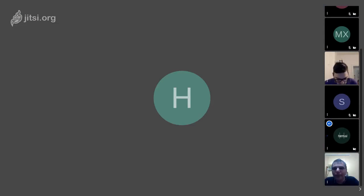So the reason I was trying to do that was I can export from the template fine, and that opens up in KiCad. But when I was trying to do it on my own, I was getting a footprint that just had the reference and the value and nothing on the footprint. But just to be clear, do I need to have the reference, value, and then the F.Silk, and those are the three things that I need? Yes. Yeah. Okay. That's true.